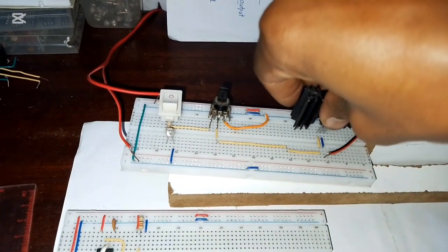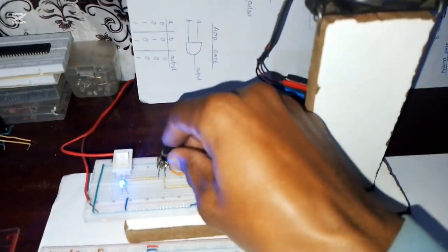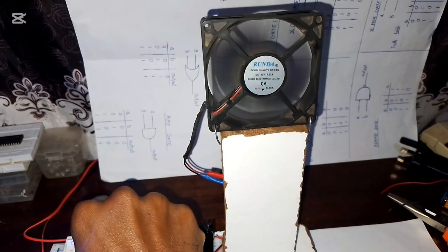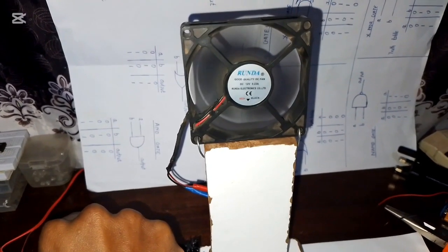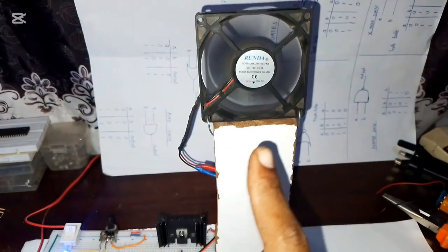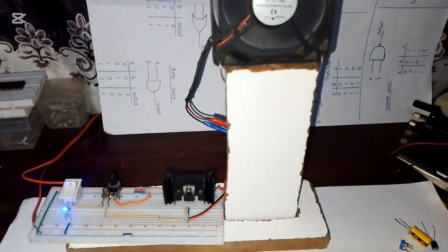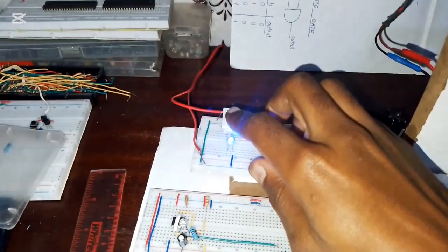Next here, it's basically how we have been connecting it. You just turn it on, and you control the speed of the fan via the pot meter wiper, the adjustment bar. You can increase the amount of voltage at the gate, and now it is running at full speed, and you can reduce it to run at maybe middle speed, like that. So this is the region I was talking about, the linear region, and it's a very inefficient point of running your system because it loses a lot of power in the form of heat. That's why we have connected the heatsink. Let me just turn it off.